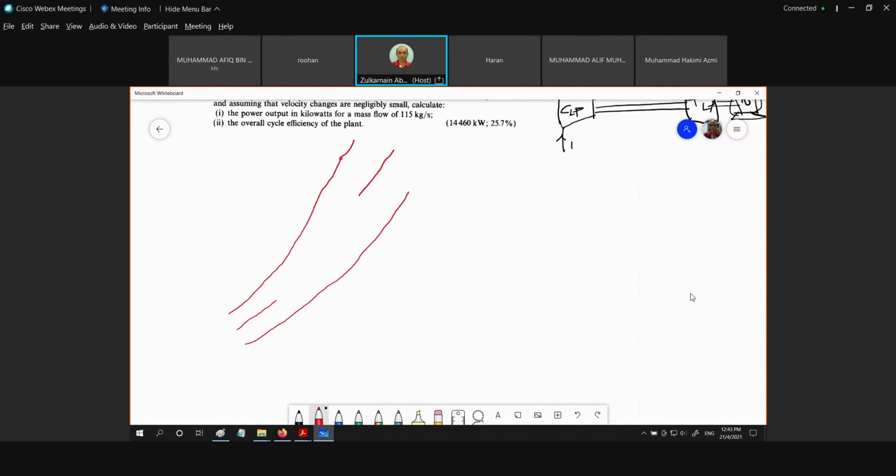The only thing that is given right here is the compression ratio for the compressor. Meaning that for the compression process, the high pressure compressor and the low pressure compressor have the same pressure ratio. Then our line should be in the middle, which is the intermediate pressure.